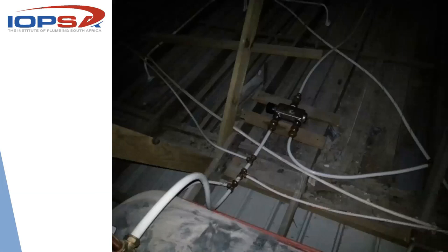Okay, so let's get back to what we're actually talking about, which is the bracketry and the securing of pipes, and why we are trying to achieve it: the prevention of certain things. First and foremost is water hammer. One of the primary causes of water hammer is loose pipes knocking against the wall, along with undersized pipes, which we know. But a pipe which is unsecured knocking against a truss or a beam or a wall or a ceiling board or whatever the case may be will make a noise.